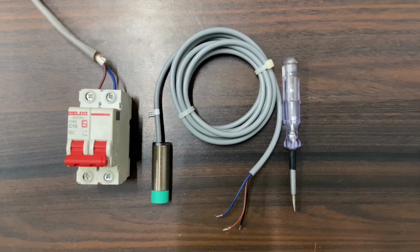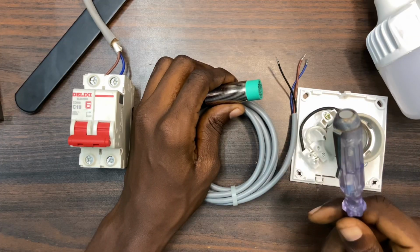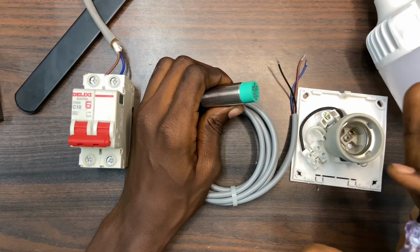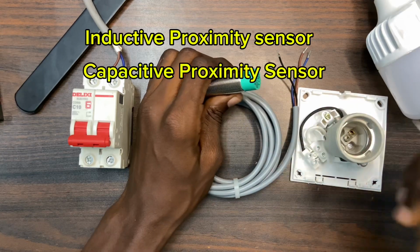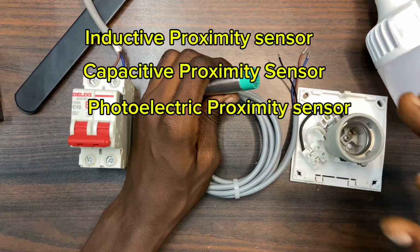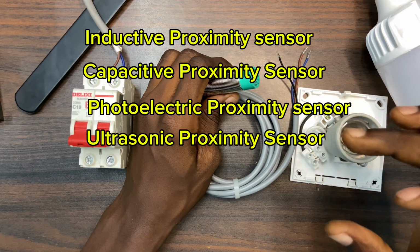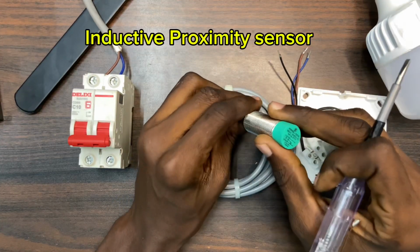That is that. And a proximity sensor is a device that detects the presence of a nearby object without any physical contact. We also have them in different types. That is the inductive proximity sensor, capacitive proximity sensor, photoelectric proximity sensor, and ultrasonic proximity sensor. We have more, but we are actually going to focus on the inductive proximity sensor. That is what I'm having right now.